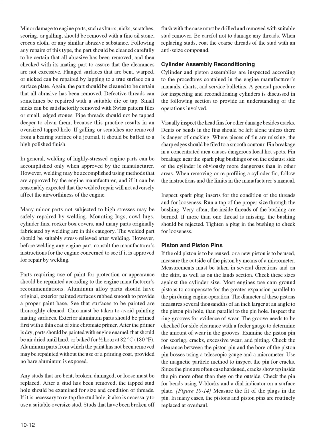Minor damage to engine parts, such as burrs, nicks, scratches, scoring, or galling, should be removed with a fine oil stone, crocus cloth, or any similar abrasive substance. Following any repairs of this type, the part should be cleaned carefully to be certain that all abrasive has been removed, and then checked with its mating part to assure that the clearances are not excessive.